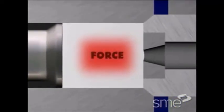Force increases rapidly as the billet is upset to fill the container, then increases further as breakthrough force before extrusion begins. Upon breakthrough, the force declines as billet length decreases until a minimum force is reached. As the billet thins, the force rapidly rises again to continue metal flow radially toward the die opening.